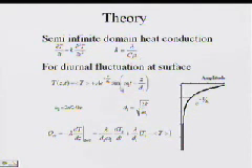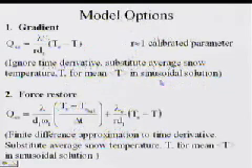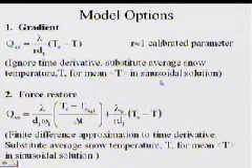We looked at the equations involved in this exponential decay, assuming you've got a sinusoidal fluctuation at the surface. And we were able to come up with some different options for modeling the surface temperature. The option we were really using was the gradient-based approach, which said the conduction was a gradient between the surface temperature and the average temperature of the snow.